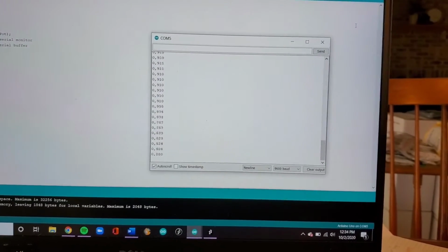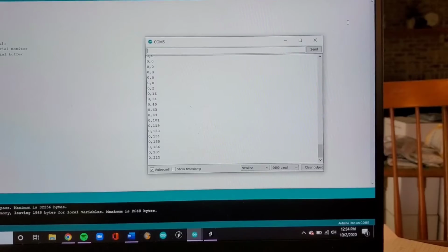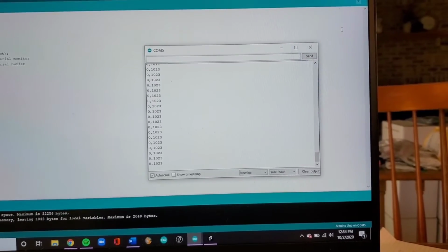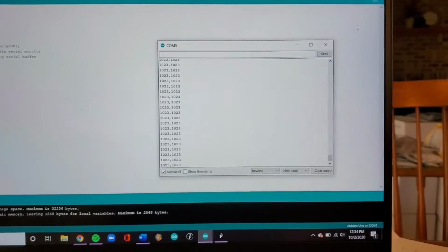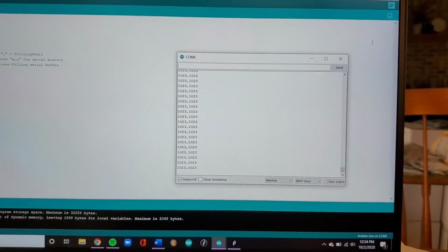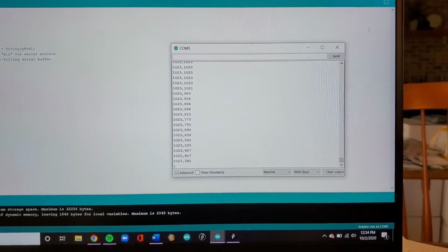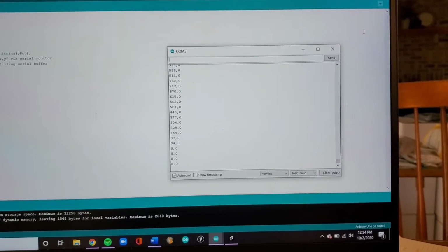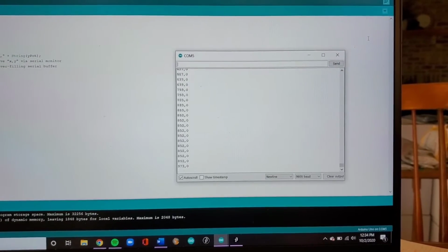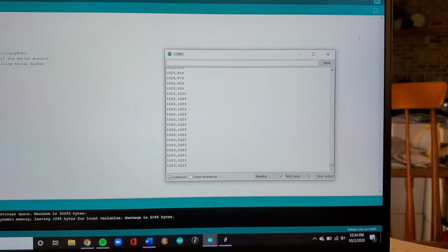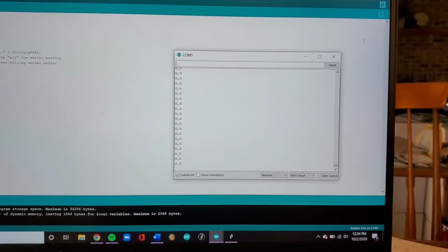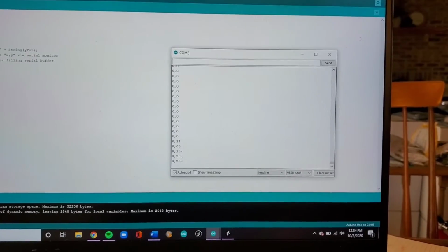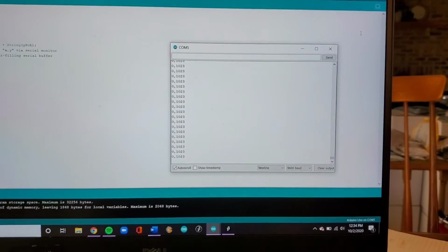So here in the serial port of the Arduino IDE, we can see that the minimum values are 0, and that's because of 0 indexing, but the maximum values are 1023, and that would be because we are using a 10-bit ADC, so the possible values are technically, according to the math, 1 to 1024, which is 2 to the 10th, and because we're 0 indexing, that makes our initial value 0, and our minimum value 0, and our maximum value 2 to the 10th minus 1.